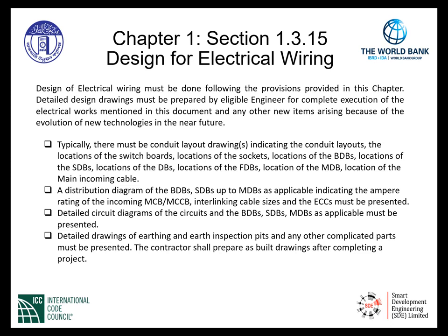Typically, there must be conduit layout drawings indicating the conduit layouts, the locations of the switchboards, locations of the sockets, locations of the BDBs, SBDBs, location of the DBs, etc. A distribution diagram of all of our distribution boards, as applicable, indicating the ampere rating of the incoming main circuit boards, the molded case circuit breakers, interlinking cable sizes, and the ECCs must be presented as well.